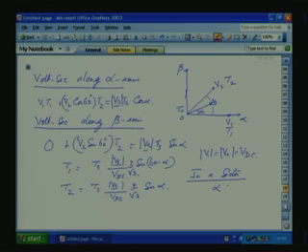alpha varies between less than or equal to 60 and greater than or equal to 0. That means it varies from 0 to 60 degrees. So we have to compute T1 and T2 for alpha varying from 0 to 60. As Vs traces a circular trajectory, this is true in other sectors also, only for the alpha, which means alpha measured from the start of the sector. Only the vectors V1 and V2 will vary in different sectors. Okay. Now, if we know T1 and T2,